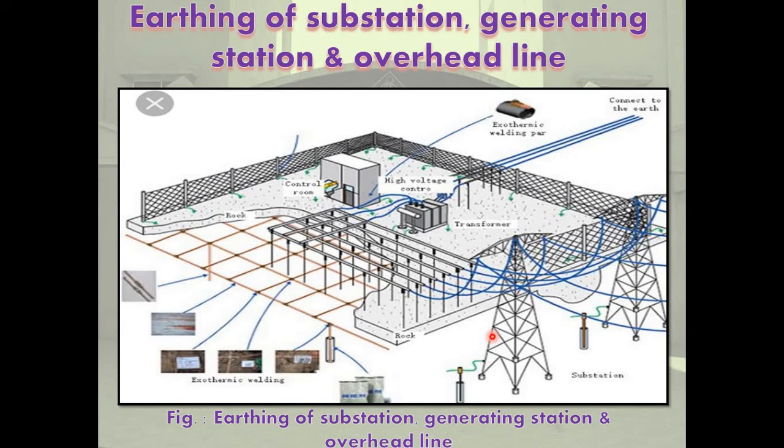Fourth one is earthing mast lightning spikes in substations and on tall buildings and towers. Zone of protection is 45 degrees with respect to the vertical line. Fifth is surge arresters, lightning arresters, connected phase to ground on transmission towers, distribution poles, substations, power stations to discharge lightning surges. And sixth is co-ordinated spark gaps, like a rod gap at the other end, connected phase to ground to protect insulators and bushings.